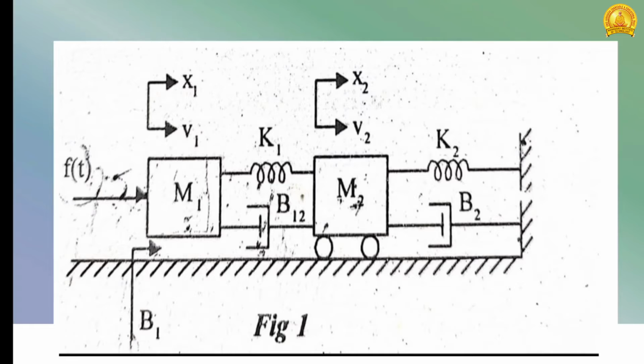For representing the differential equation, the first step is to draw the free body diagram. For drawing the free body diagram, first we have to find the nodes. In a mechanical translational system, we normally consider the mass as the node. In some diagrams the mass may be missing, and a dashpot and a spring may be connected.